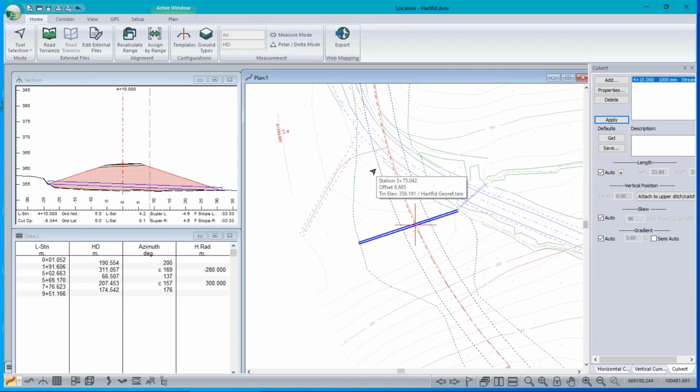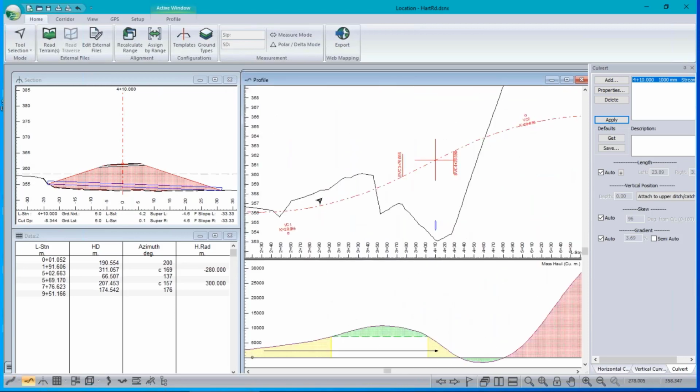So hopefully you can all see my screen, and you can see that we've got a little road example here. It's a road realignment, and we're looking at, in the profile, you can see we've actually got a little bit of a gully here. I put a culvert at the bottom. And this is an application for a cross-section template because we don't want to have this giant fill and this stupidly long culvert here. We'd like to do something different.